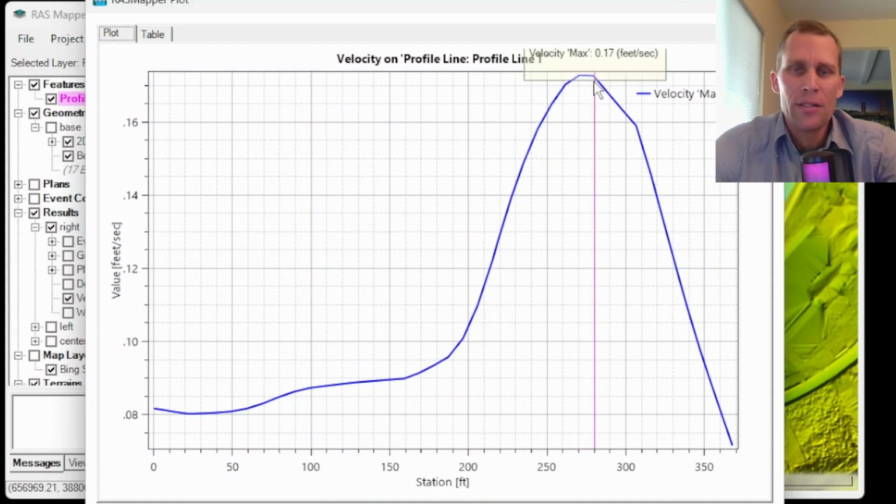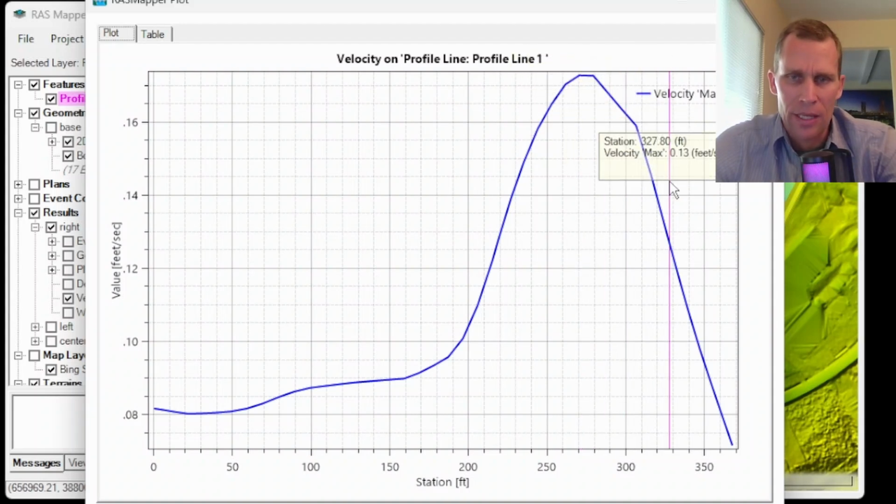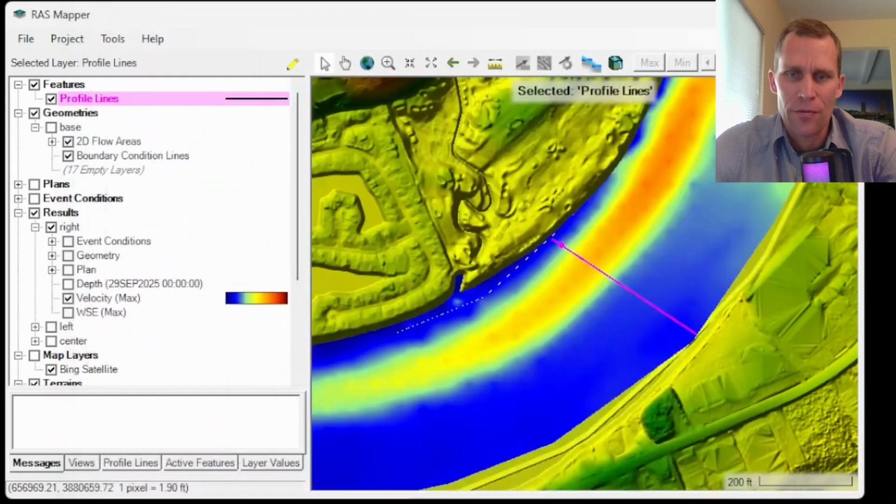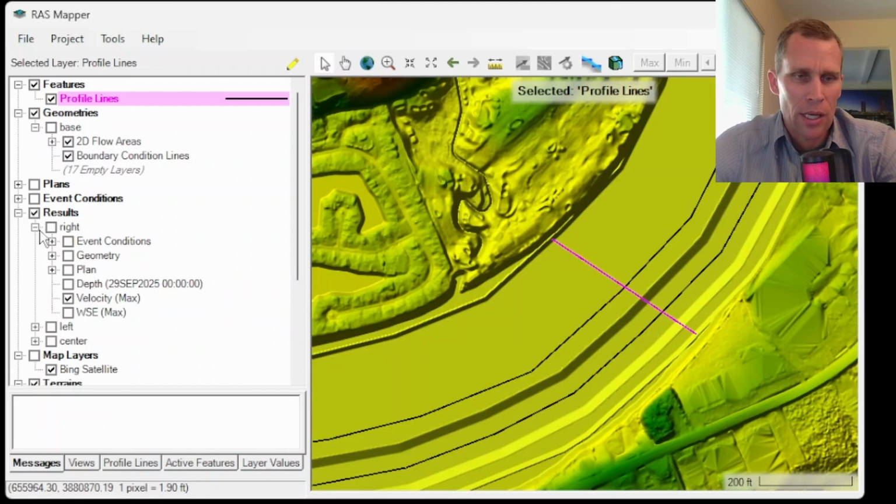Now, in reality, channels are not typically deeper on the inside. Typically, if there's any curvature to the river, it's going to be deeper on the outside. There's going to be more erosion on the outside and more deposition on the inside. And hence, that's why meandering rivers like these ones with not much slope tend to continue to carve out in the outside reach direction.